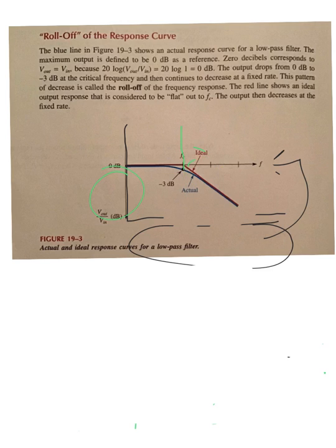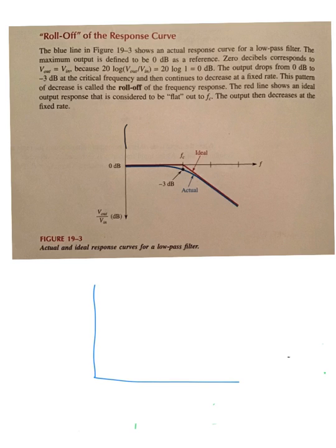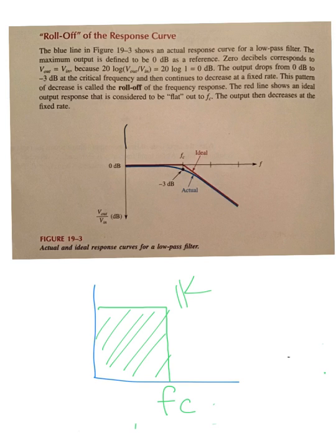down. Now, minus 20 dB looks really good until you ask yourself, well, is that really what you want from a filter? And the answer is pretty much no. What you'd rather have from the filter is a cutoff that drops at a given frequency. So, in other words, let's say this frequency is at 1K, then anything below 1,000 passes, anything over 1,000 dies very quickly. But what happens is the filter leaks.